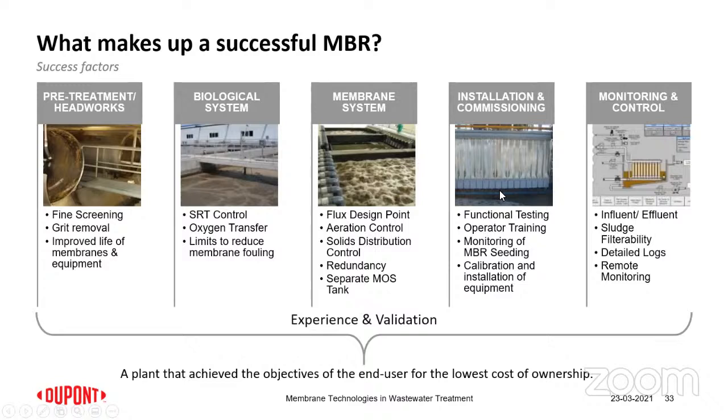well it's been installed. Is all the equipment that is required for monitoring in place at the time of commissioning? Were the membranes properly flushed, and are they properly cleaned prior to operation? Is the calibration of instruments all proper, then monitoring. Membrane suppliers do provide guidance on control philosophy, operational philosophies, and the equipment requirements. So it should all be incorporated as something that needs to be taken into control.